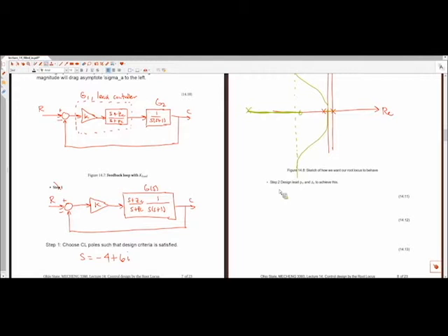Like every other semester I've taught this, all students are going to hate this rule of thumb because, of the rules of thumb, it's probably one of the more wishy-washy ones, but the general rule of thumb is to place ZC approximately equal to omega n desired, right? And then from there, calculate PC to ensure root locus goes through the correct point.